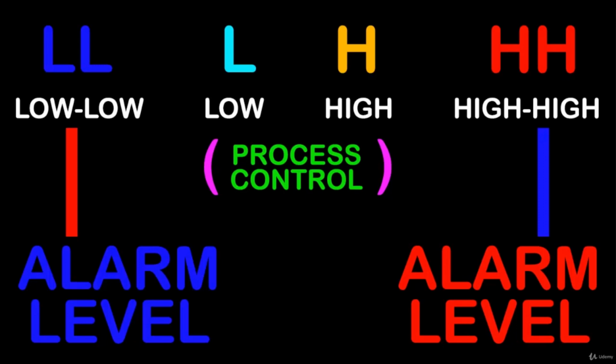We'll say it's 60 degrees outside. Well, eventually our temperature in our system, being read by our thermocouple, is going to fall down to 70. Once the temperature falls below 70, our heater will come on, and it'll stay on until the thermocouple reads the high temperature of 80 degrees. At that time, our heater will turn off, and it'll stay off until we fall back down to our low.